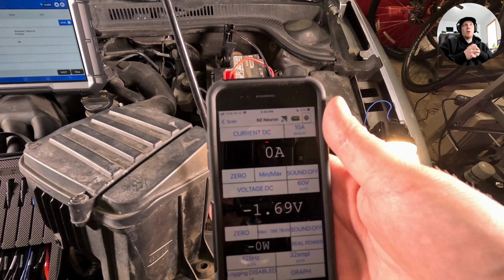That's something that you might be scratching your head if you know anything about voltage drop and going, wait a minute. So what is it actually telling us? It's telling us that there is a difference of voltage between the positive terminal at the battery, which should be about 13.8 volts because that's what our T30,000 tornado is putting out, and what it is measuring down at the connector where the headlight plugs in. So 1.69 volts is quite a bit of a difference.